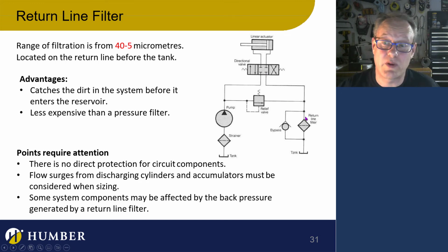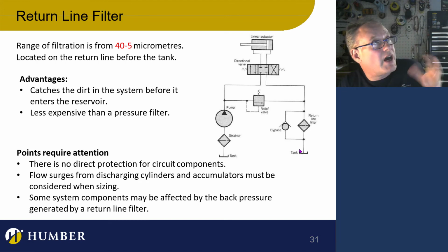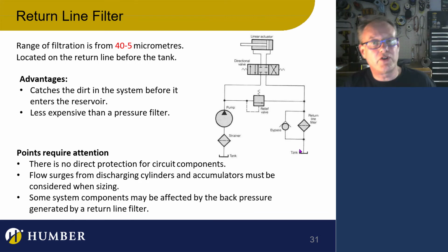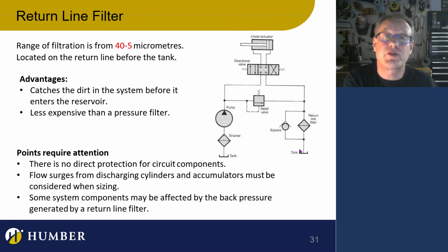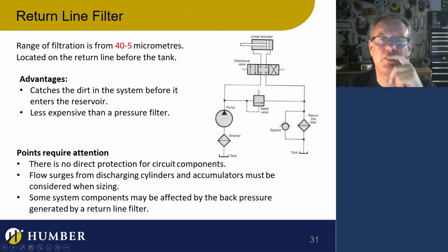Like I said, this thing is stealing 80 psi from the system, and that's okay. It's like a pressure line filter in that it's on the return line, which will actually be under pressure, because the filter itself says, I need some of this energy that you're pushing this fluid through with, and pressure will actually be generated on the upstream, pardon me, on the downstream.